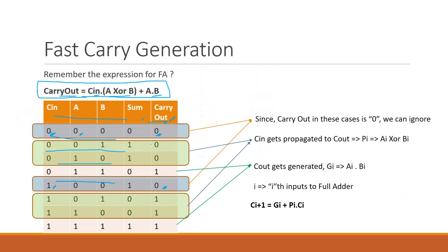So next combination, if you see, for the combination of A and B being either 0, 1 over here and over here, these four combinations, Cin is 0 in the first combination. And for this combination of AB, the same Cin comes out as Cout.